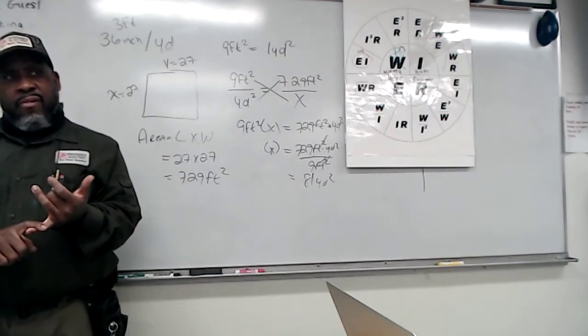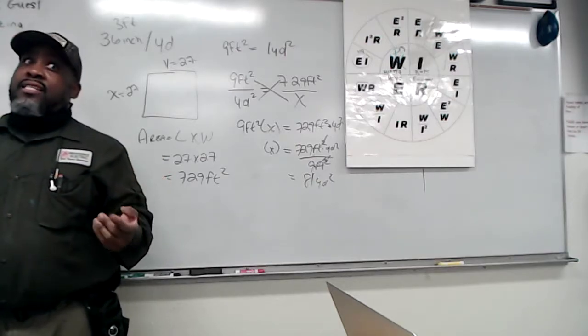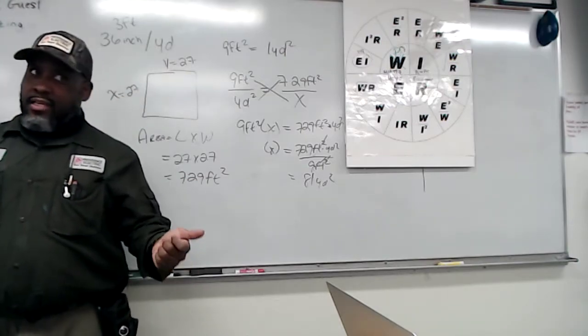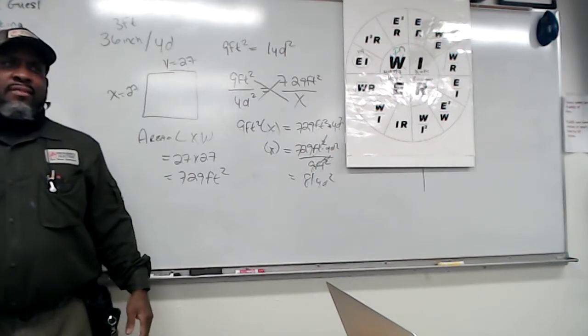A kitchen has different requirements. You got to have a dedicated circuit for a microwave. You got to have a dedicated circuit for the refrigerator. You got to have 2 appliance circuits in there. Then you got to have certain plugs on the countertop, a certain amount of feet away from the sink. It's a total different set of requirements. Does that make sense?